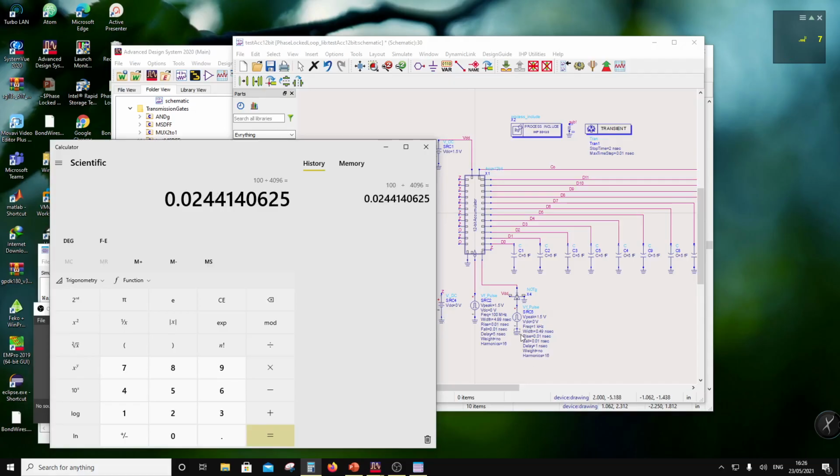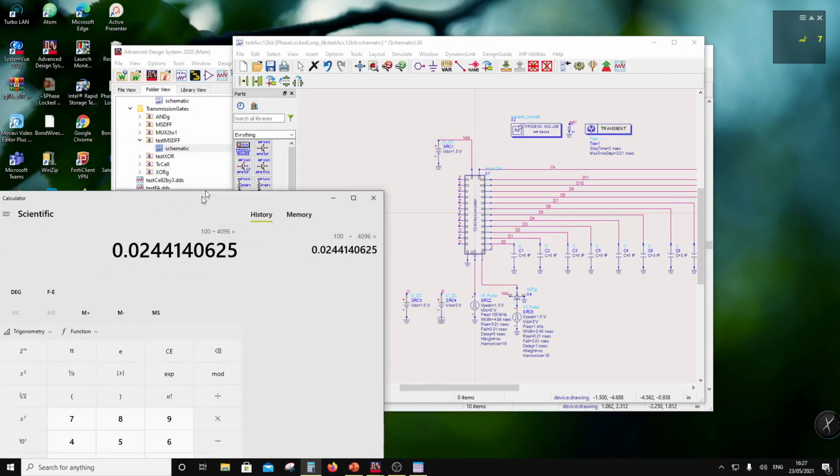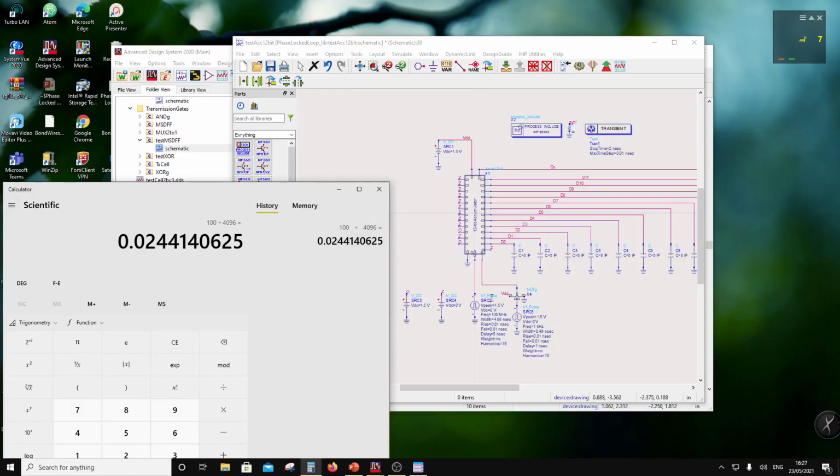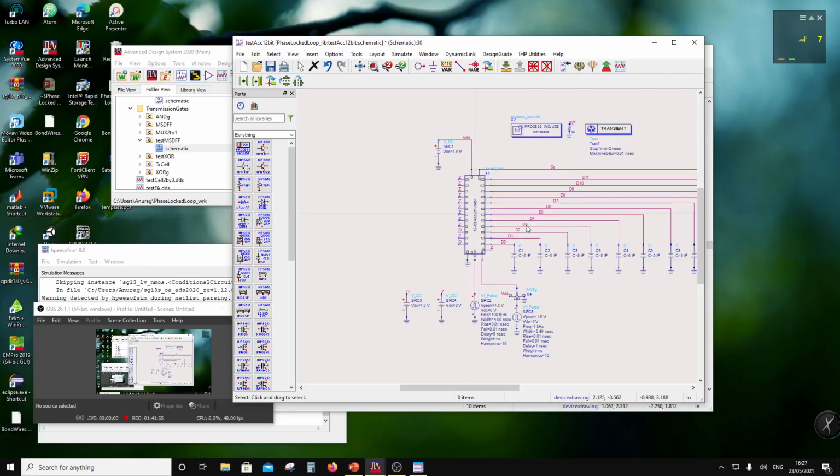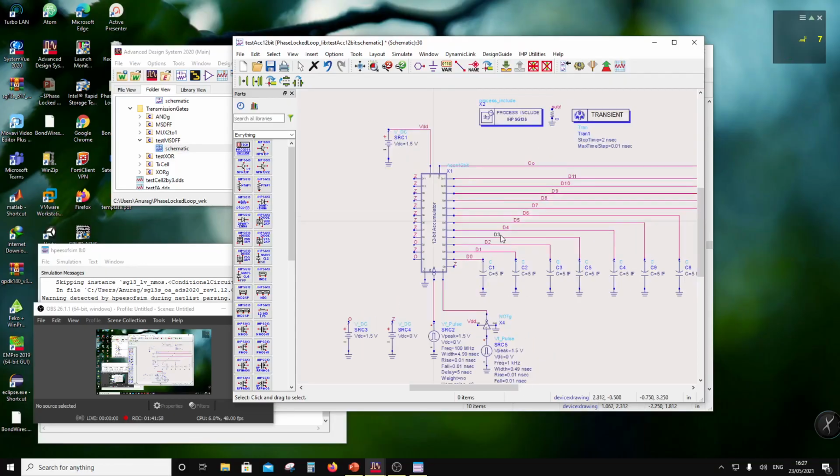So at this point the load will come again, or not the load, the clear will come again, or I may not need to clear it even. So once I do this, it'll automatically keep in loop, right? So that's fine. It's just when you set this PLL in the starting sequence, you should put one pulse. It's a mono pulse, and once this is done on clearing, then whatever is the input, you can keep adding. Now if you change this input, you have to introduce this pulse again. So that's when you program the PLL.